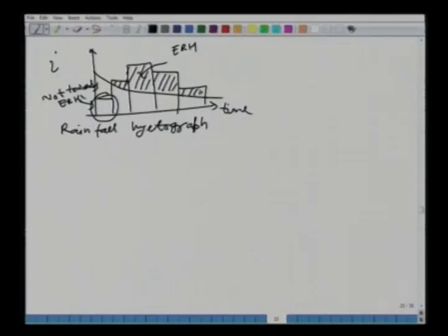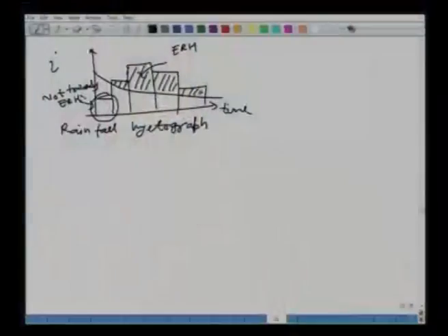Okay. So, you see that we have looked at this algorithm in which we have the rainfall hyetograph, and we can convert that into effective rainfall hyetograph by subtracting losses due to infiltration using Green-Ampt equations. Okay. The algorithm which we have developed does not account for the initial abstractions, we had said that earlier. However, if we have the initial abstractions estimated somehow, they can be incorporated before infiltration can be subtracted. Okay. So, that way we have done half of the rainfall runoff modeling as far as calculation of the losses is concerned and calculating the effective rainfall is concerned. And then we can go either to the unit hydrograph or any other complicated rainfall runoff model, but we will not start that yet. Okay.